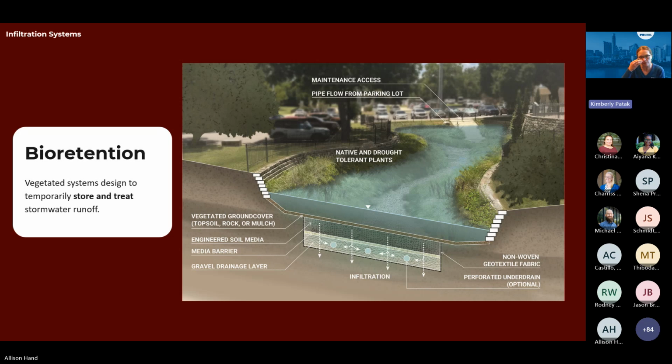So think of it as, if you're designing your site, all the runoff from the site would drain to this regional control, or at least a component of your storm drain system, the main line, would outfall into your bioretention system. It is a dry facility that temporarily impounds water, just like a rain garden, and can be customizable for the design to meet your site's needs. And also even customizable for the vegetation practices, just like with a rain garden.